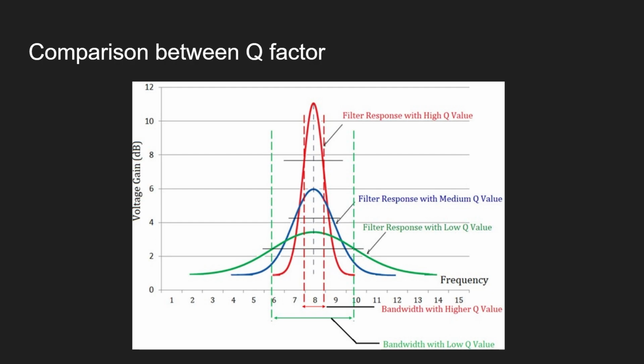If your antenna responds in a very, very narrow range and the gain is very high at this point, we say that this is a very high Q factor. Selectivity means they will only respond to or receive the signal in this tiny gap. This is what we call selectivity: only choosing a very small range of frequency.